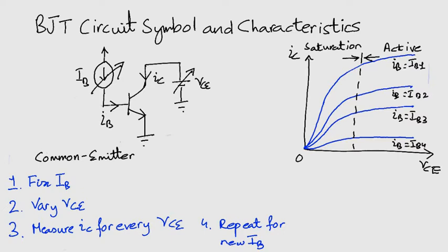Here we are, IC versus VCE. You can clearly see the two modes, saturation and active. This is, however, an expanded graph and not the full graph. Why? Because near the IC axis, the graphs are bunched together. We, however, have to make one important observation here.